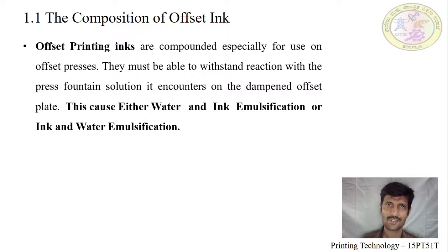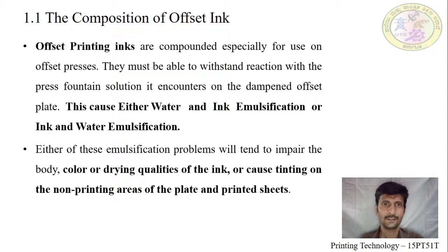Finally, it transfers down to the non-image area of the plate so that scumming will occur in printing and it creates faults. And the emulsification also gives drying as well as tinting on the non-image area and creates gum problems.